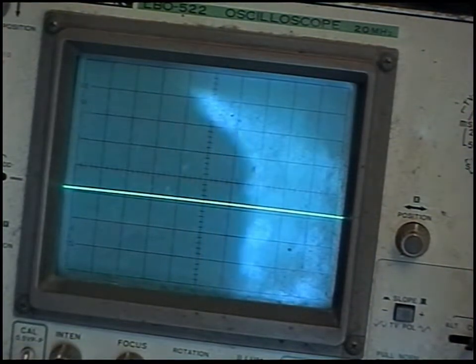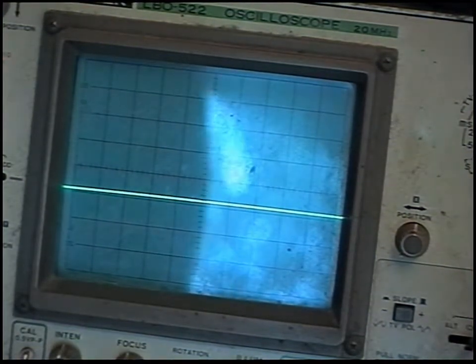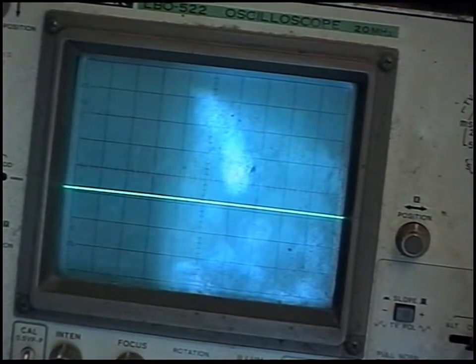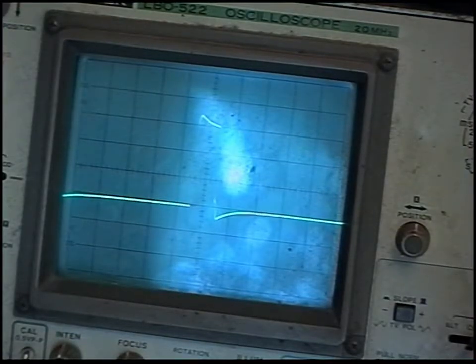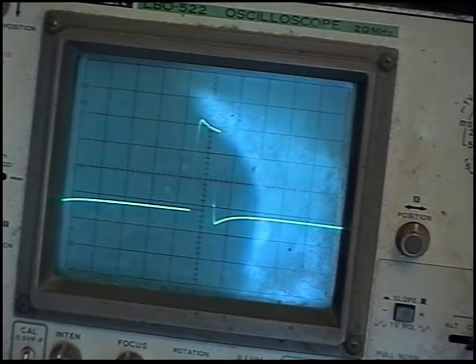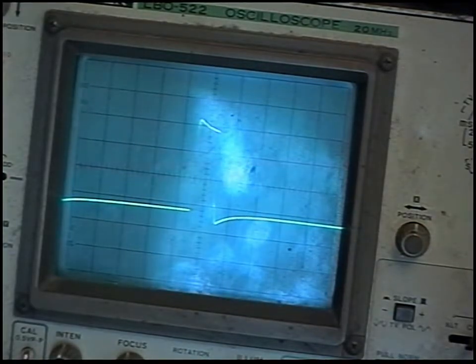Right, so I'm going to now measure the horizontal and vertical drive signals from the chip, and that's the horizontal drive signal, and that looks right. It's 2 volts per division. It's supposed to be 6.3 volts peak to peak, and that's at line rate. Everything looks fine.